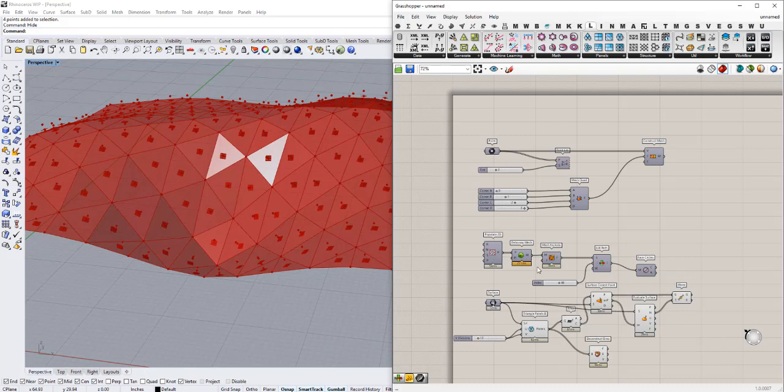I could go through in the same way that we made the triangular mesh for all of these, but that would be extremely tedious, right? But one thing we have is, if you look at these vertices, we have a separate branch for each face with the 3 points. And we also have a plane. So we could use a Delaunay mesh along that plane to generate the right topology for these pyramids.